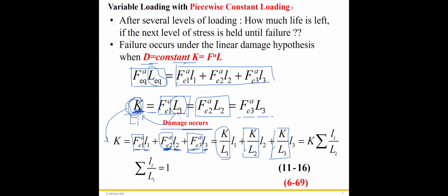So we can extract the K outside, and we get K, the damage, times the summation of lowercase li over the life capital Li. Then we have to obey this equation: K equals K times the summation. Therefore, this term has to be 1.